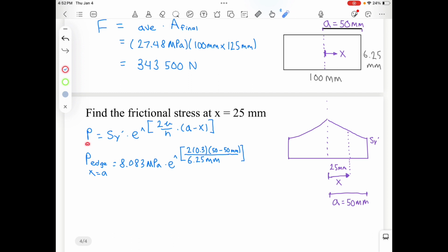So when we use the formula for pressure at a certain point, we've got A minus x. Now that's relating to A, half of the distance, minus x, the position we want to see. In this case, where we're calculating the pressure at the very edge for our minimum pressure, we want to find A minus x, while x would be all the way to the edge. So A and x are going to cancel out, meaning this whole term will cancel out, and we'll be left with the same thing as the plane strain yield strength.